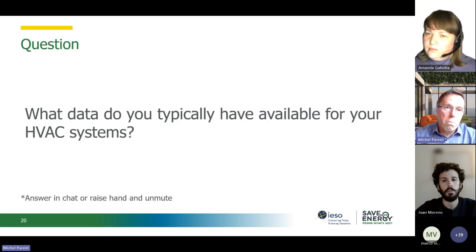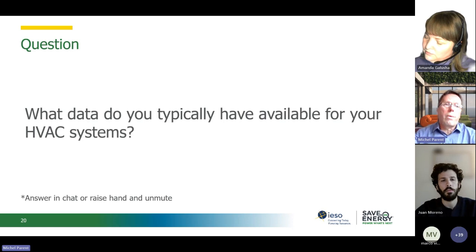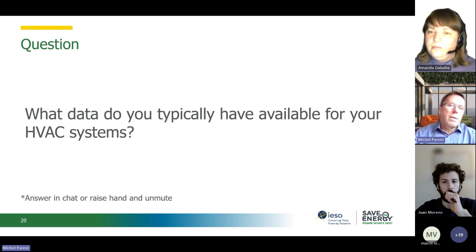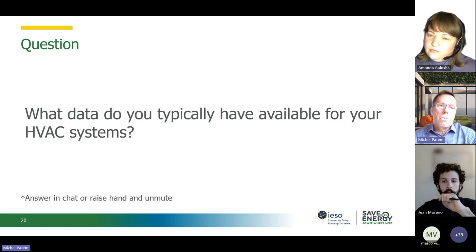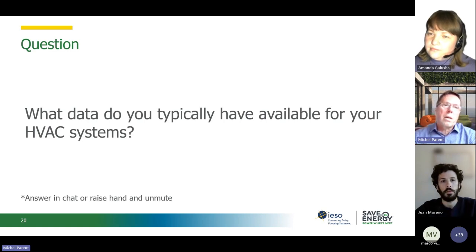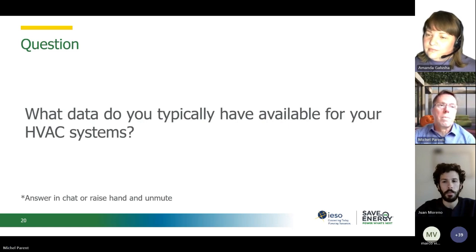Unless you take any other measures, you could decide to redo a whole building load assessment, or you could say, hey, I had a 1.5 ton unit, I'm going to put back a more efficient 1.5 ton unit. So by knowing what's there, it will give you guidelines on what you could be replacing it with. Unless you do other measures, like I said, you change windows, you insulate walls, then your whole load calculation will change and you'll have to start from scratch, basically.